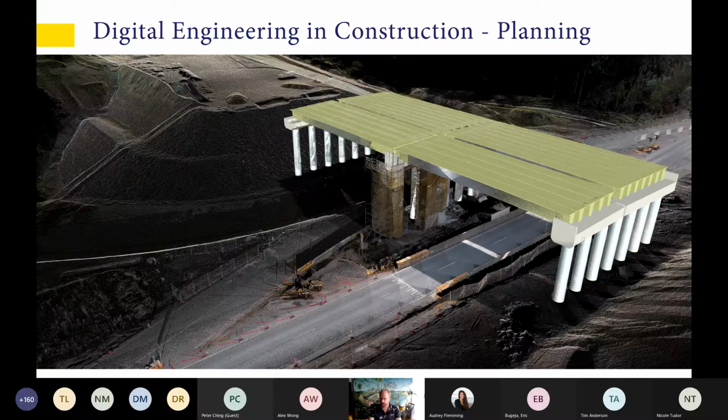This one is actually another end of the same job. What you're looking at there is UAV data, basically for anything that's off the road, and MLS data on the road, and so it's RTK pickup. I think with the road we're getting under 20 millimeters accuracy, and with the UAV with the RTK pickup I think we're getting under 70. So it's usable stuff, and surveyors are getting used to using mesh, solids, and point clouds now, so not a big deal for us.